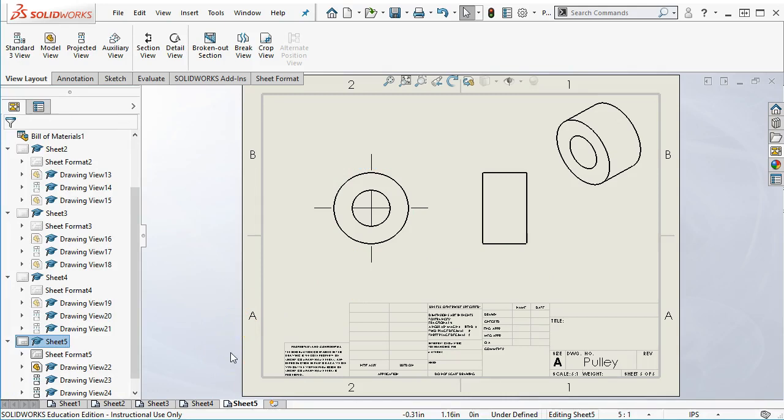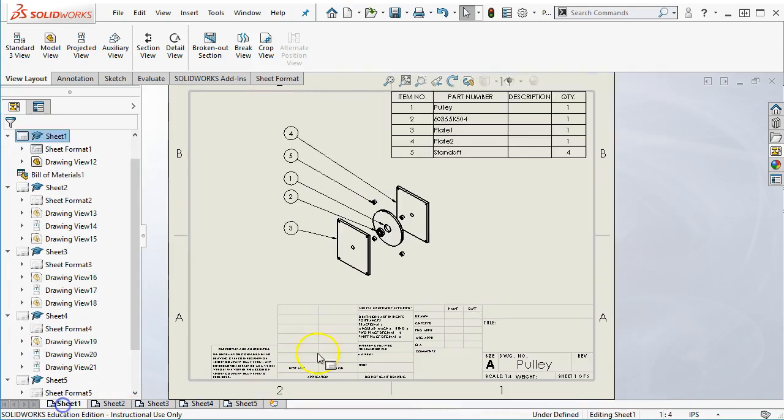The purchase pieces are, we get what we get. We're not going to go through in detail unless there is a modification to a purchase part to make it work in our assembly. So if I buy it, it's off the shelf and I'm just going to put it in and assemble it. I don't need to reproduce the drawing. I want to have those items documented as far as the part numbers or a description, something that will show up in the bill of materials that gives it traceability.